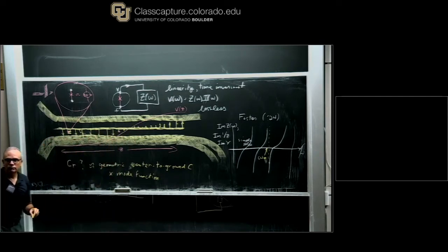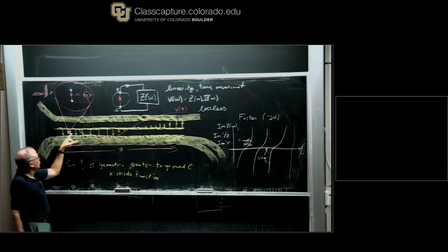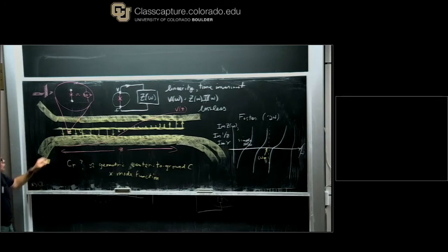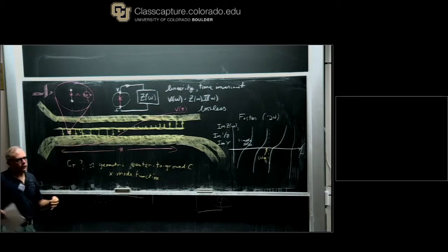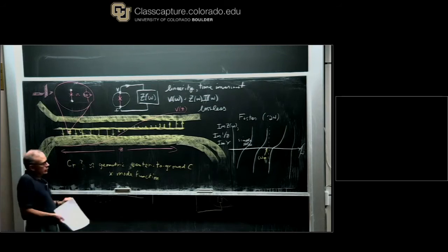So it is in fact determined by the strength of the local electric field of this mode at the point where the transmon is. So that says it's not just a simple capacitive geometric quantity. It inherits knowledge about this finite frequency, high frequency mode pattern, but that's only approximate.